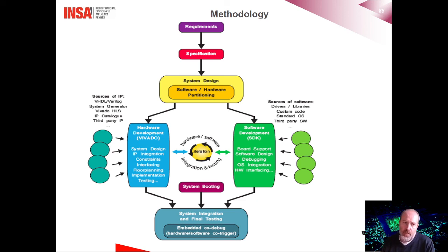After that, it's then possible to implement the full design in an FPGA. The bitstream file is first downloaded to the FPGA in order to download first the processor and the peripherals and all the hardware blocks in the circuit. And once this is done, it's possible to download your application software in memory, where the code will be found by the processor to execute your application.